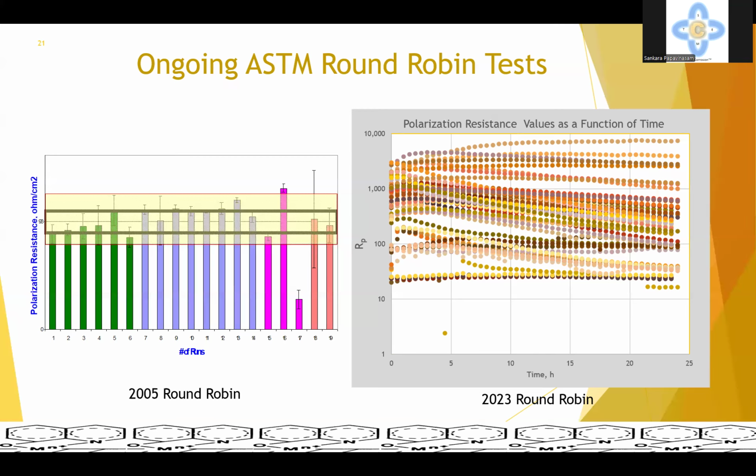They consistently used the same procedure, and this is the data point they got. Again, polarization resistance is the inverse of corrosion rate. So that did not meet the ASTM standard in terms of establishing precision. So we restarted understanding what is going on with the rotating cylinder electrode.